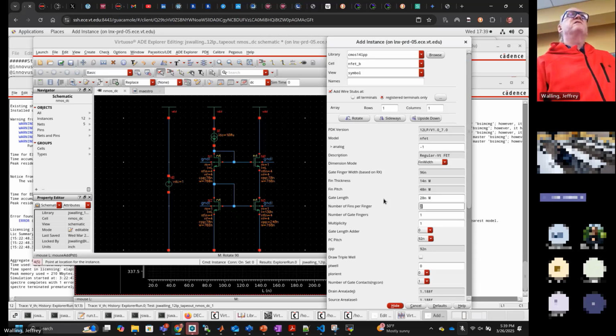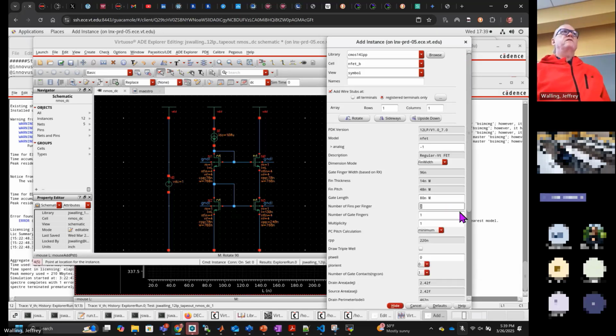See, I tried to put 30 in, and it forces it to 28, and I think the next step was like 80. Yeah, so anyhow, it turns out that the way we change the length in a fin device, we tend to stack devices. It's easier to stack them, so that's much more common with fins.